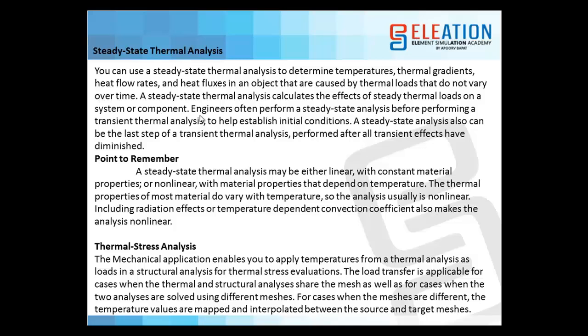So we are performing a steady state thermal analysis where we are not changing the temperature with respect to time, but in transient thermal analysis, we can give the inputs where we can change the temperature with respect to time. So a steady state analysis also can be the last step of transient thermal analysis, performed after all transient effects have diminished. Points to remember: a steady state thermal analysis may be either linear with constant material properties or non-linear with material properties that depend on temperature.